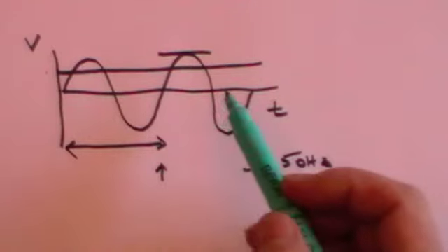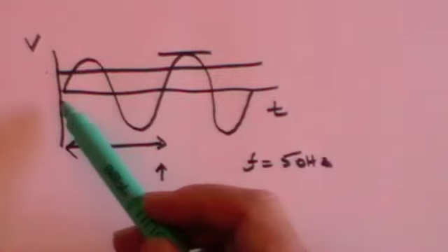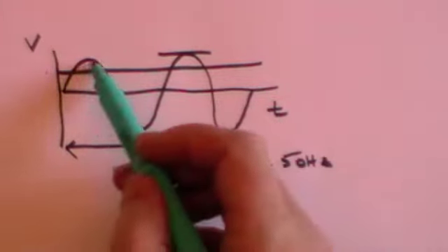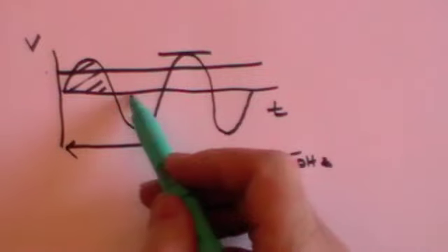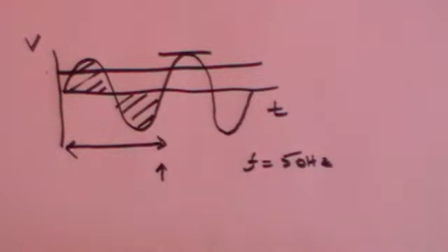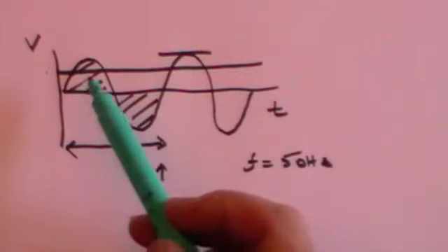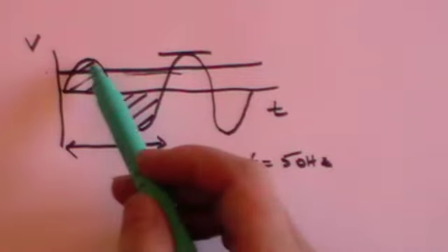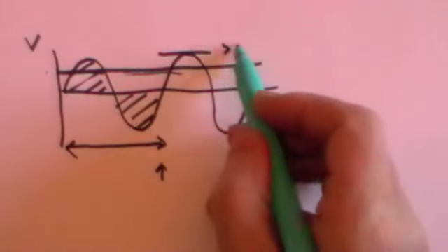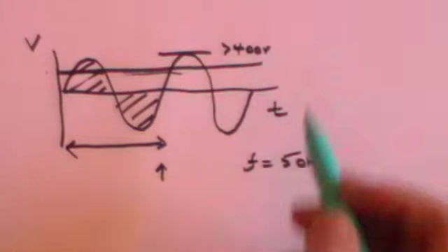It's not the absolute average, of course, because the absolute average voltage is 0, because there's a positive half here and a negative half here in one complete wave, and the two would cancel out. So the average is strictly 0, but the weighted average, which is called the root mean square, sits somewhere along here, and the actual peak is over 400 volts in a domestic supply.